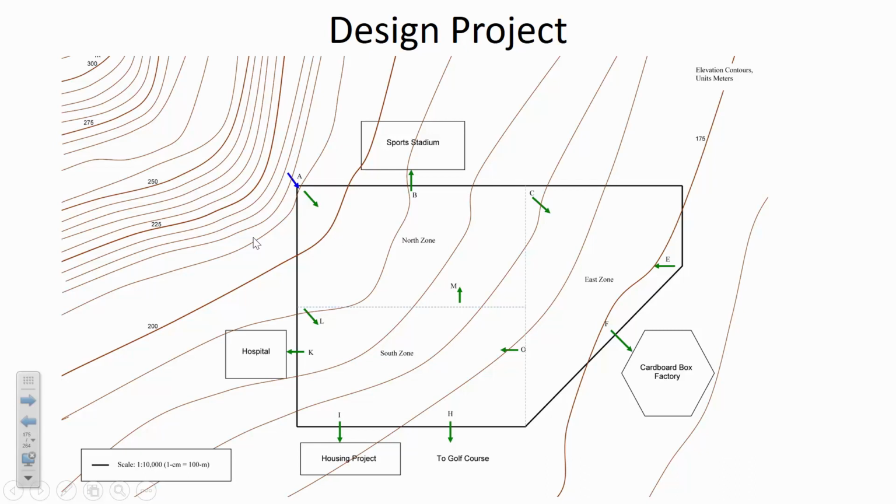The way you're going to pressurize your network is you're going to put a reservoir somewhere up on this hill. If you know how to read contour lines, you'll notice that the town is sloping downhill in this direction. So this is uphill, and somewhere on this hillside you're going to place a tank of water to pressurize the network. If you look around in this area, you'll see that same exact thing. There are big green tanks on hillsides, and that's what provides pressure into people's homes.